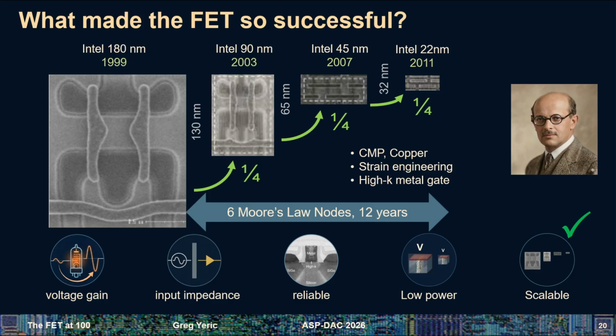A major thing in industry was an uncertainty about how to do the processing of this new material. You could put the dielectric down first and then the gate, which sounds obvious, but there's also a way to put a dummy gate down first, then remove that and do the dielectric. Intel and TSMC at the time picked different ways to do it, gate first, gate last. TSMC picked wrong, and that's why they had to quickly go from what they were calling their 32 nanometer node to a kind of half-step 28 nanometer node to go back and fix it, because they just made the wrong bet and they got behind.